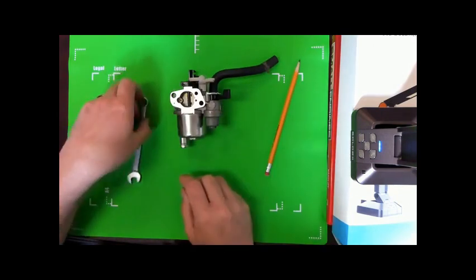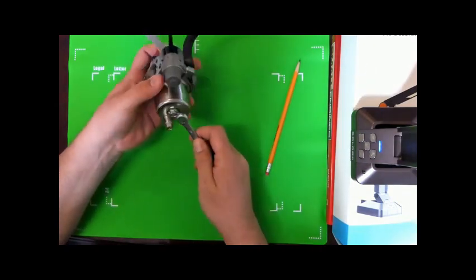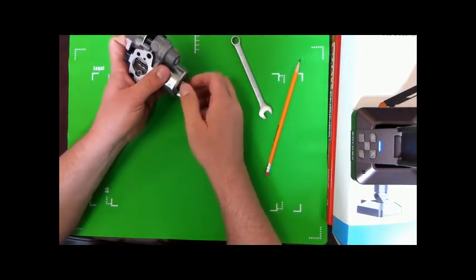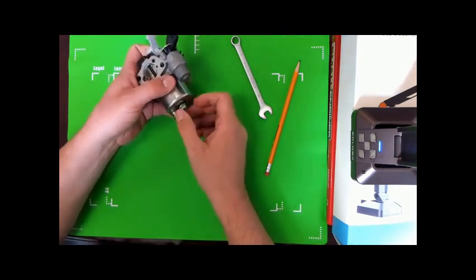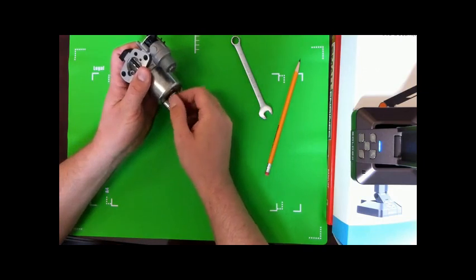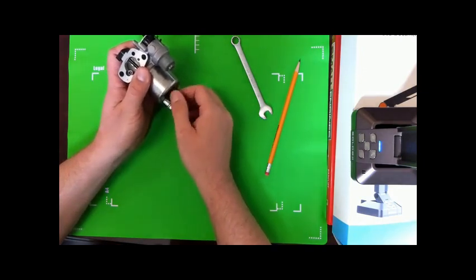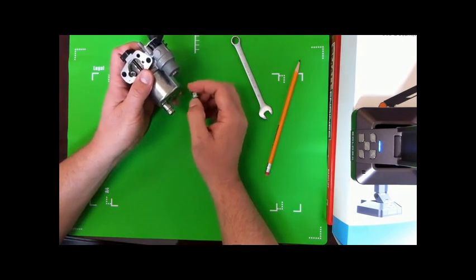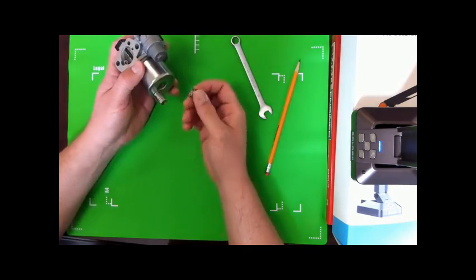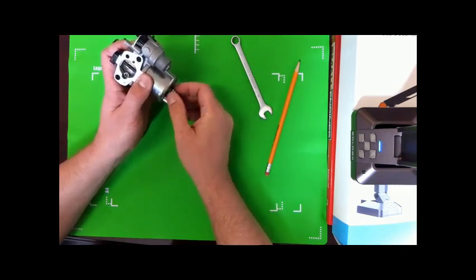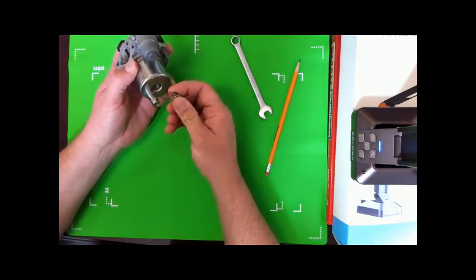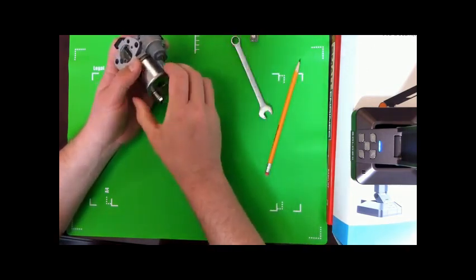All right, so as we take this carburetor apart, I've got my 10mm combination wrench. Most of the bolts on these engines are 10 or 8mm. One thing I'll stop on real quick, you can tell on this carburetor that this is simply the bowl nut because it is silver. Sometimes you'll find these are brass, and if you're one of my LSU students familiar with the small engine CDE, our 900 series have a brass screw right here, and this brass screw as a bowl nut is actually the main jet, again, if that is brass.